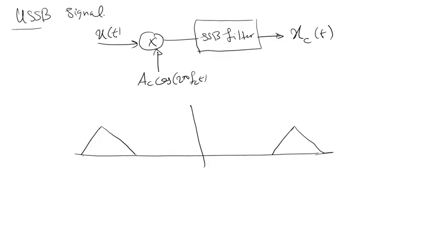In the frequency domain, you multiply by the frequency response. So assume the frequency response is this red one. You can remove this sideband and hold this one, and here also you can hold this and remove this one by using this filter. So by filtering we can have the SSB spectrum.